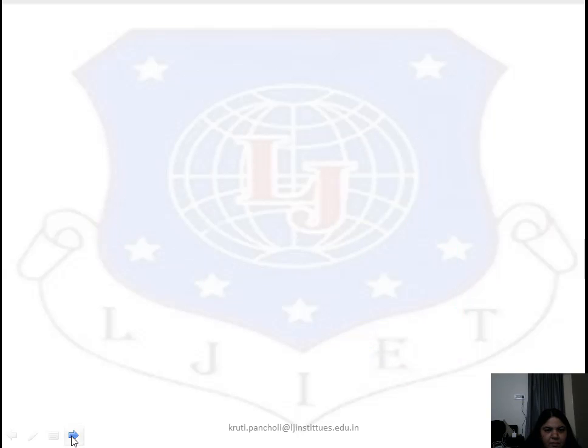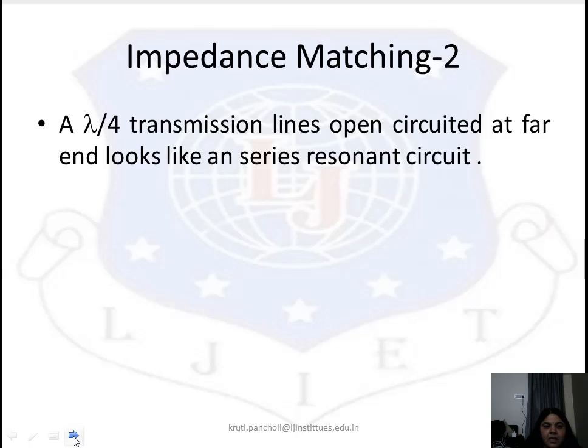Now next, in the impedance matching 2, a lambda by 4 transmission line open circuited at far end looks like a series resonant circuit. So now that will behave like a lambda by 4 transmission line. So this is my lambda by 4 transmission line which is open circuited at the far end. Okay, so this is open circuited.